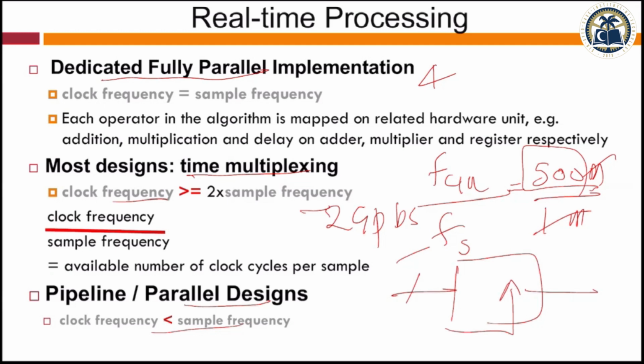If there are multiple streams, then you can always put one stream here, one stream here, one stream there. But if it is just one stream of data, you have to figure this out within the stream. That is a very, very challenging problem from the architectural perspective. Let's say in networks it is just a packet you have to process, and you want to do it 4 times the data rate. So what do you do?